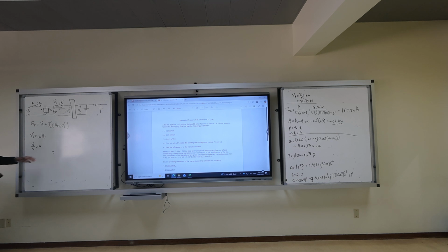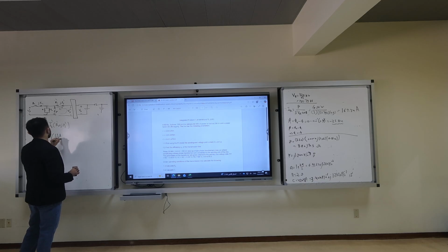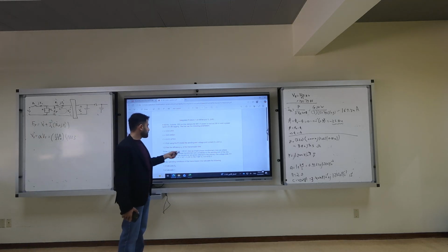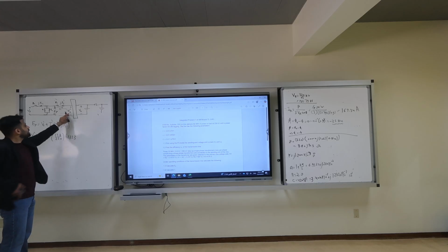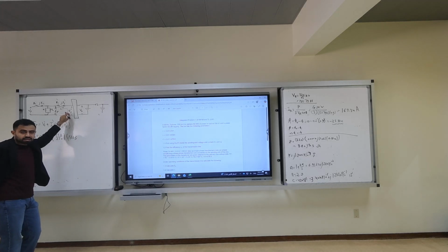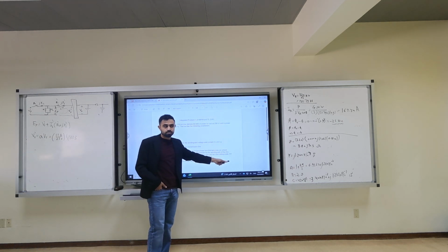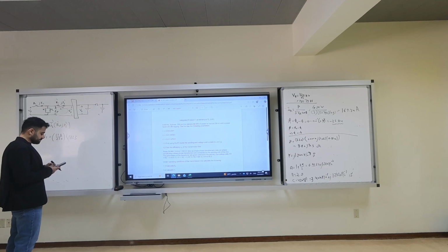Go back to the slide. So what is A? 13.8 over 230, step down. What is VS? 133.3. No, it's written here. Yeah, step up. Sorry, step up. That means VS prime will become bigger or smaller than VS? Smaller, because it is referred to the primary, referred to primary voltage. What was the voltage of VS? 132. No, 133.